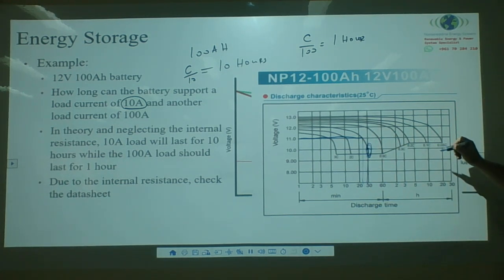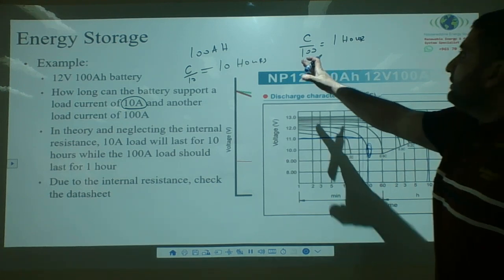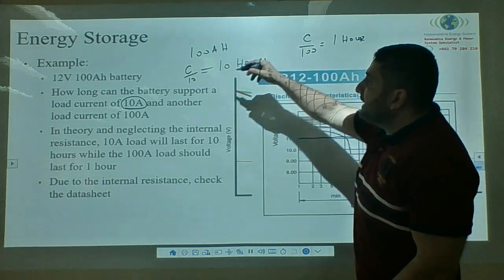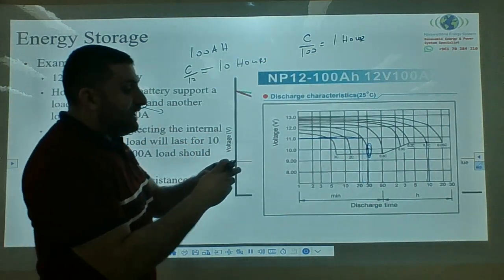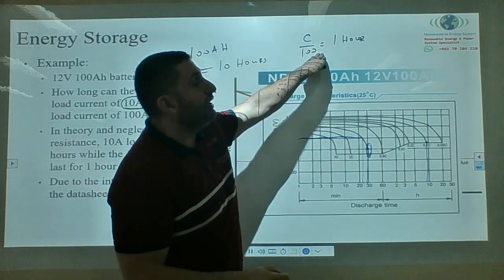When I use 10 amps, guys, see, it's just under 10 hours. So the lighter the discharge current, the closer I will be to the theory.